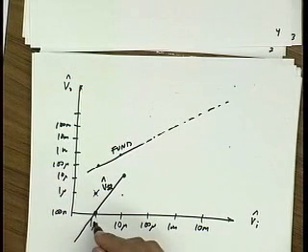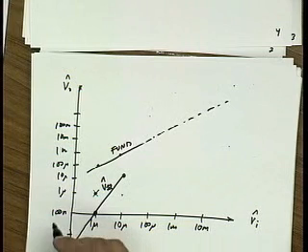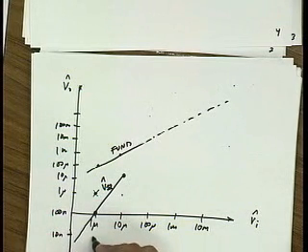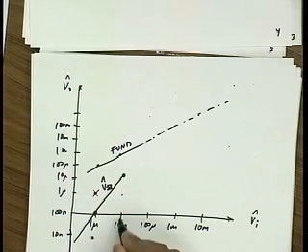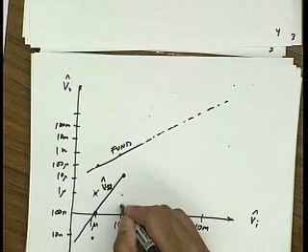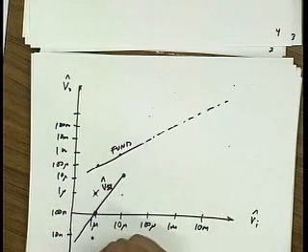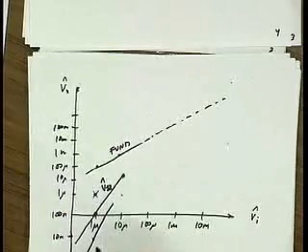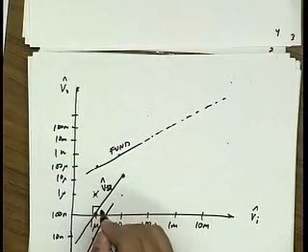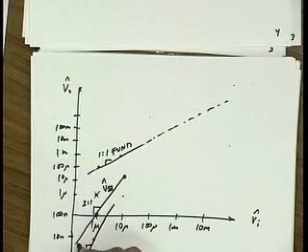Likewise, if I look at the third, let me expand this curve here. This is 10 nano. Let's say my third is here. If I increase the input by a factor of 10, what happens to the third? Well, I think you get the point. It's cubed, so it should increase by a factor of 1,000. So my third harmonic has a slope that's 3 times as big. So this is 2 to 1, this is 1 to 1, and this is 3 to 1.